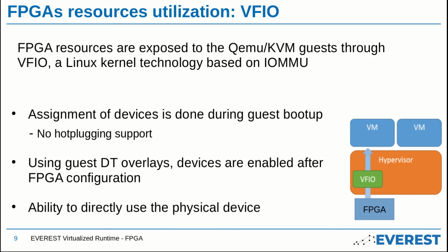For ARM FPGA devices, each and every device should be pre-assigned to guests at the moment of their bootup. The reason behind this is because the VFIO platform driver of QEMU, which will be used for our kind of devices, does not provide dynamic hot plug capabilities, as it happens for instance on x86. This comes, however, in contrast to the dynamically programming logic that we would like to support.